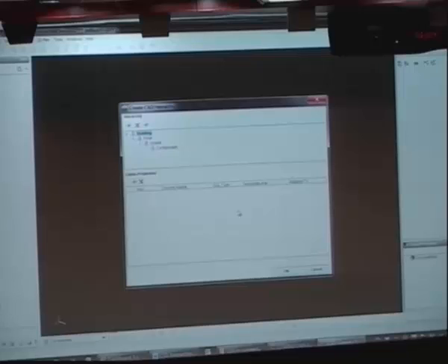So I just create my tree structure on the fly, and then you can set the data structure that you want. For the sake of this example, I'm just going to keep it simple. I'm going to give the object class just an ID, which is coming from the member mark, the tag from BIM, which floor and which building it belongs to.